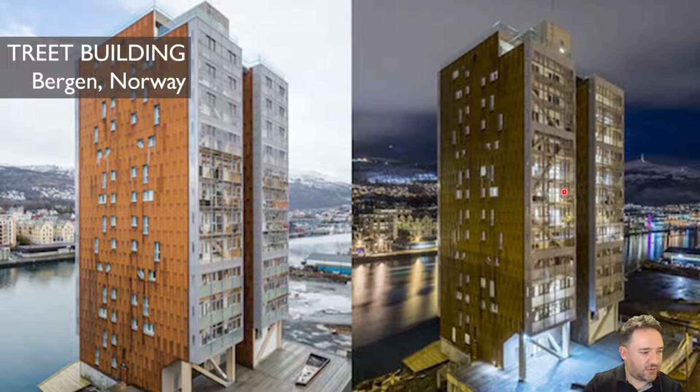This is a really tall timber building in Norway, and all these braces are all wood. You see these braces down here, you see braces down here, and these braces go all the way up. So they've got an interior structure of pods that are the living spaces, and then on the outside they've got this timber diagrid structure, providing lateral support, which they have left exposed using these windows so that you can actually see that it's timber.